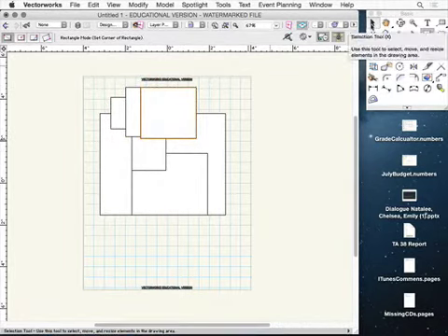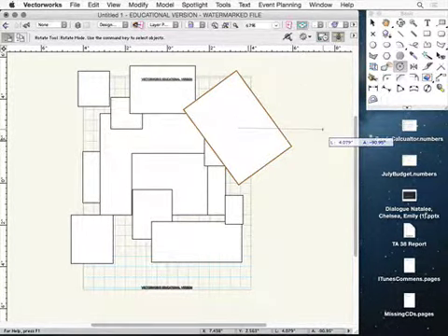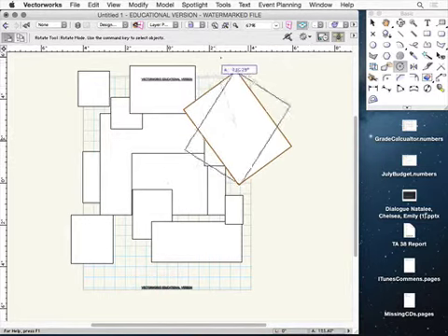This one takes 3 clicks. You know that because there's 3 little red dots. So you first draw the bottom, and then you draw the side, and now you can get it at an angle. Let's say that I had this drawn perfectly, and then I realized that, oh my gosh, it's at the wrong angle. I can adjust that by using my rotate tool. My rotate tool works like this. My first click is wherever point I want to rotate about, and then my second click creates a line, and now I can rotate it around that point wherever I want to go.